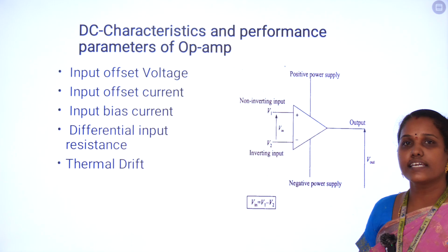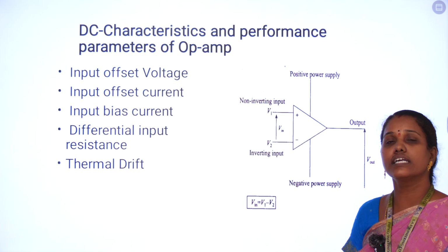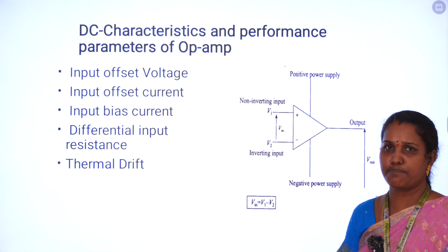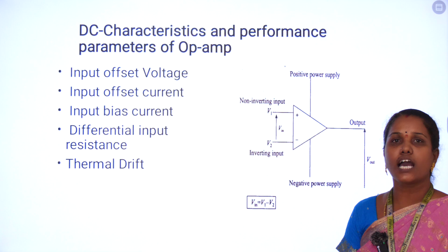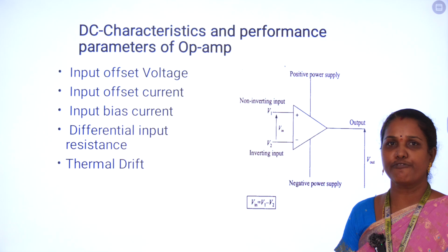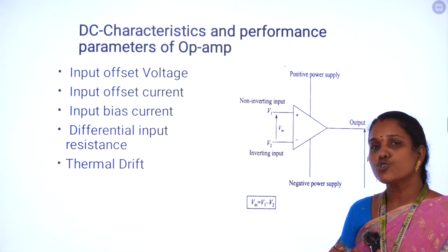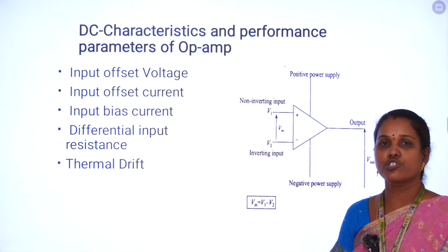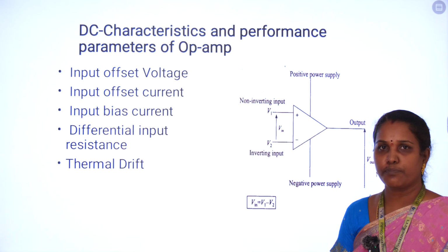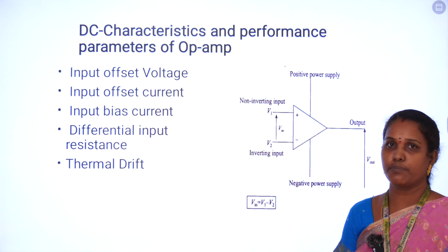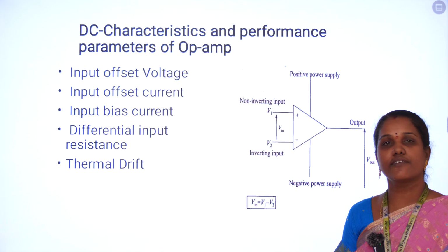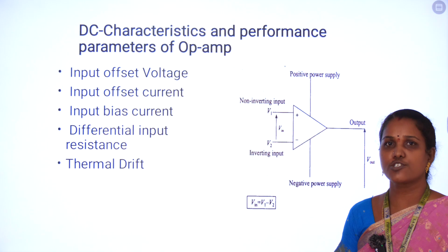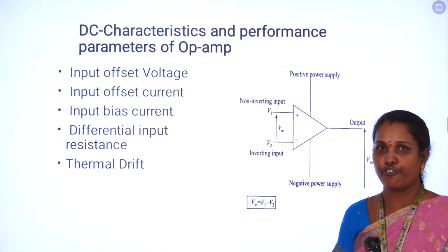You want to analyze the characteristics of IC741 in a DC manner as well as the AC manner. What do you mean by that DC manner? DC manner means your ideal IC741 operational amplifier has two stages of differential amplifier inside it, because you can assign two input terminals, inverting and non-inverting. Next is the level translator, then the output stage. These are the internal blocks of IC741.